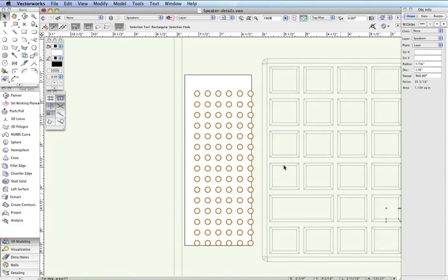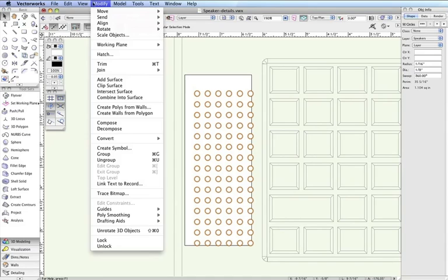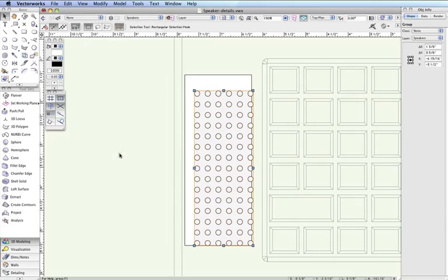So these circles are easier to move as a unit, go to Modify, Group. At the moment, your group most likely does not sit inside the rectangle we drew earlier. It will only take a few steps to align these objects exactly. Your group of circles should already be highlighted, so press the X key to switch to the Selection tool. Then hold down the Shift key and click the rectangle behind the group.